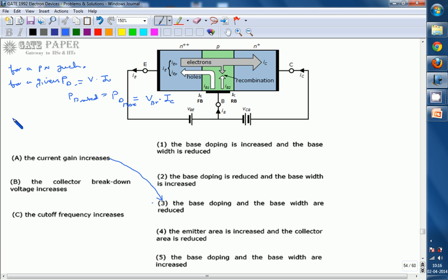As collector current decreases, for the given maximum power dissipation, the breakdown voltage across the collector has to increase to maintain the power dissipation. For the given power dissipation, the breakdown occurs at larger voltages whenever the collector current is reduced. Otherwise, for larger currents, it occurs at smaller voltages.